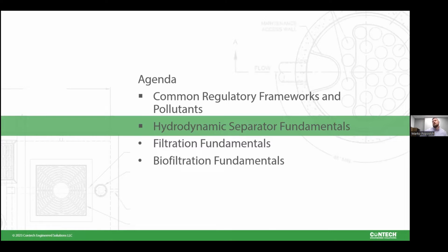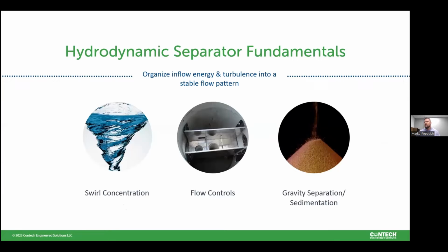Thank you, Vaco. So we're going to move into the first of our three treatment categories, that is hydrodynamic separation, which you will oftentimes hear us call HDS. So bear with me as I use a number of acronyms. I will try to elaborate on what each of those stands for. Hydrodynamic separators are based on three fundamentals: swirl concentration, flow controls, and gravity separation, which we'll refer to for the purposes of this conversation as sedimentation.